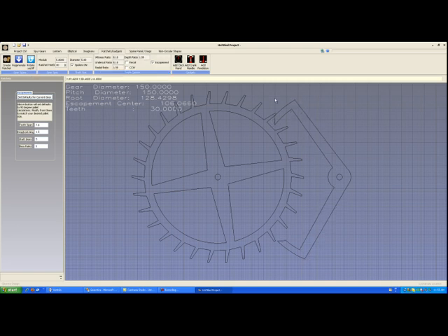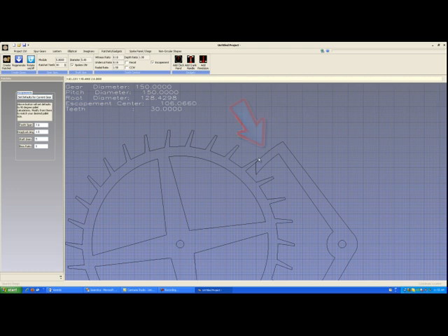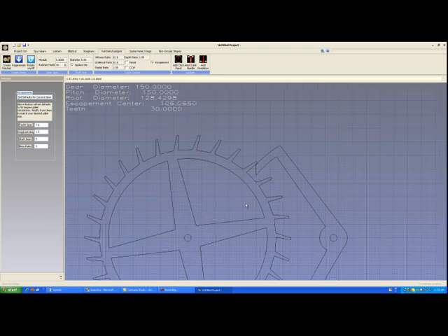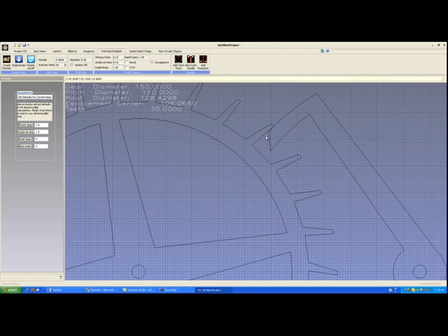Let's talk a little about the pawl here for a second. This arc here is called the lock face, and it's there for this tooth to hit on when it springs in. It is a mistake to have an escapement where the pin actually hits this face, which is called the impulse face or the pallet impulse. This pallet should only be hit when the tooth is running off of a lock face, and then it runs along the impulse face, adding energy to the pendulum. It forces this pawl to swing clockwise, thus pushing the pendulum, adding a little bit of energy.